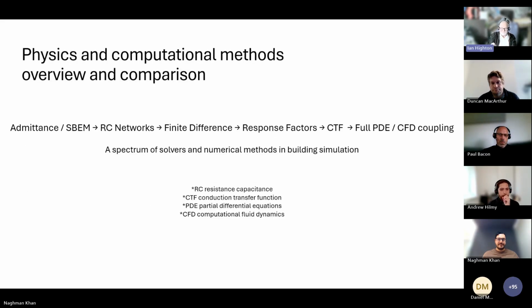The final bit is that, at the moment, we do one-dimensional heat conduction through these surfaces of a zone, and we can couple that with the CFD modeling, which is here and now. Ideally, eventually we'll have a full solution of the heat conduction in 3 dimensions for the fabric, and the only thing we'll be pulling in from the building simulation will be the adjacent zone air temperatures. At the moment we're pulling in surface temperatures, then doing the CFD, whereas eventually we hope to be able to do the full thermal analysis of the actual fabric in 3 dimensions.